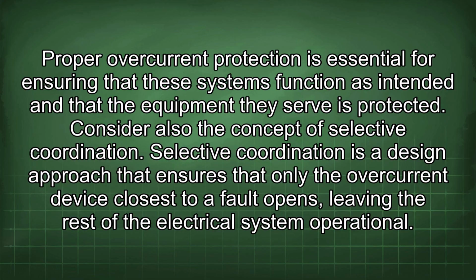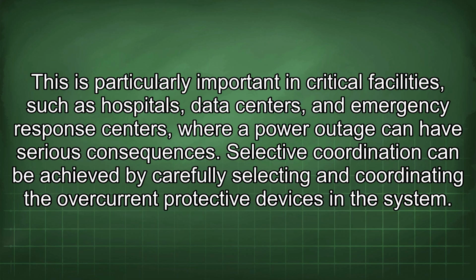Selective coordination is a design approach that ensures that only the overcurrent device closest to a fault opens, leaving the rest of the electrical system operational. This is particularly important in critical facilities, such as hospitals, data centers, and emergency response centers, where a power outage can have serious consequences. Selective coordination can be achieved by carefully selecting and coordinating the overcurrent protective devices in the system.